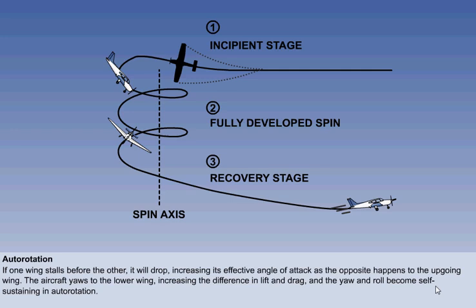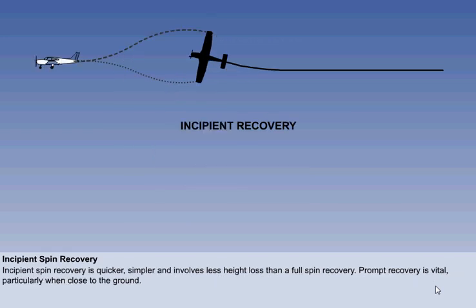As with any stall, the nose will drop, and as inertial forces take effect, the spin usually stabilizes at a steady rate of rotation and descent. It is vitally important that recovery from an unintentional spin is initiated as soon as the spin is recognized, since many aeroplanes will not easily recover from a full spin, taking several turns before recovery action takes effect.